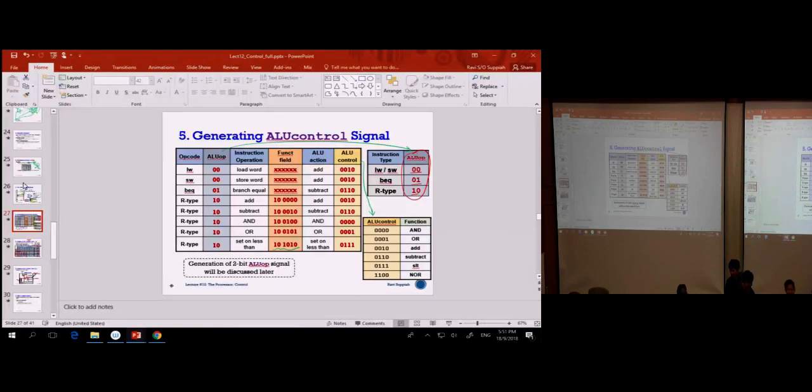I thought we just took the number and then took the very last bit and processed it into the simplified form. But that is the raw data, right? A and B. To make it two's complement, after the B invert, I still need to add one more 1, correct? Carry in. Okay, but then you get 10. 1 plus 1 is 0, carry 1. Then you carry 1 over. Eventually the answer is correct, because 0 minus 0 is still 0.